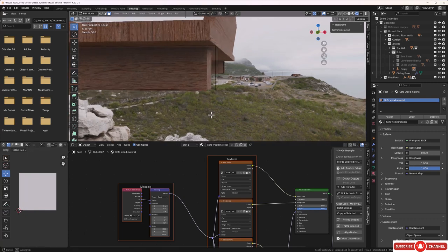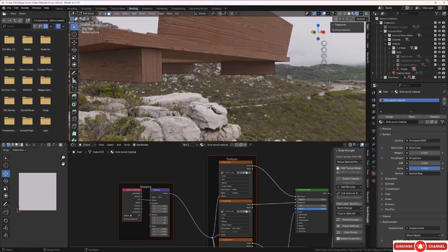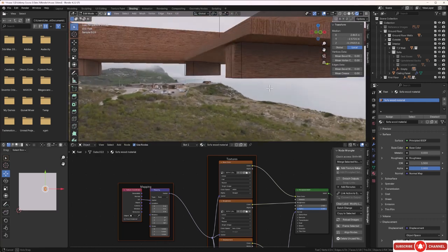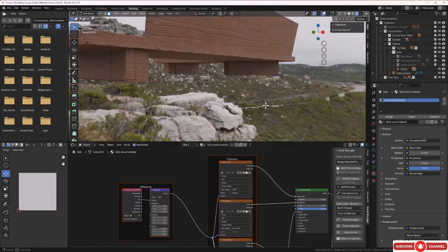And let's see what that looks like. And that's looking pretty good. So we need to actually turn these ones because the grain directions don't run through. So let's grab this one here and this one here, and let's try rotating those about 90 degrees. And that's looking better that way now.